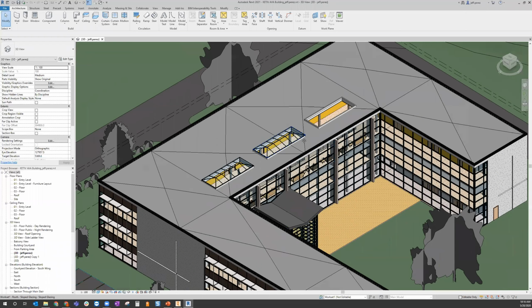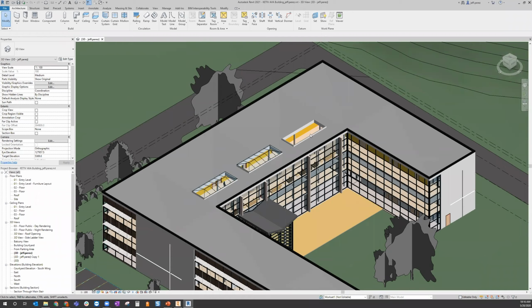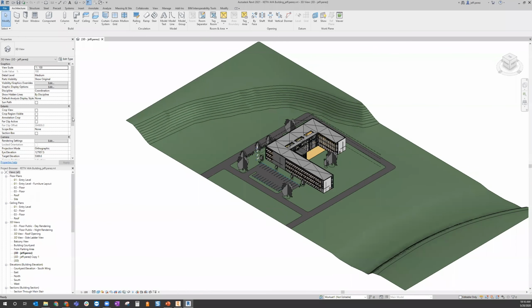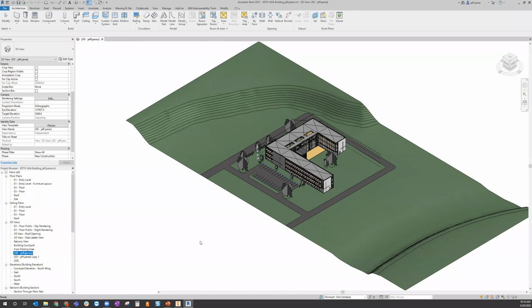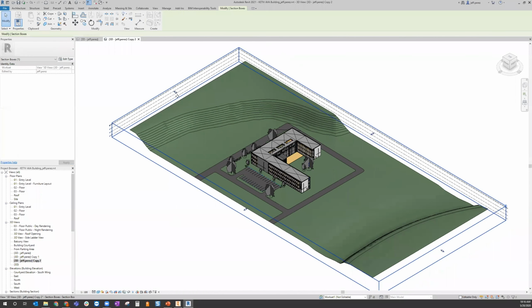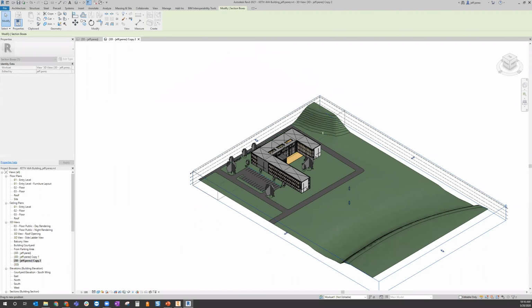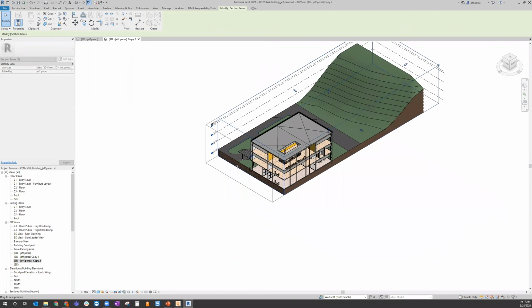So before I start my initial design, I'm going to want to size my design based on the ceiling space. So within Revit, I'm going to have Revit set up a custom view for me. And to do that, I'm just going to duplicate this view with detailing really quick. And I'm going to turn on my auto section box. Now, what I'm going to do here is change my sectioning so that I'm viewing specifically the area that I want to work in. Okay, so in this case, I'm just going to cut down to this ceiling space over here.